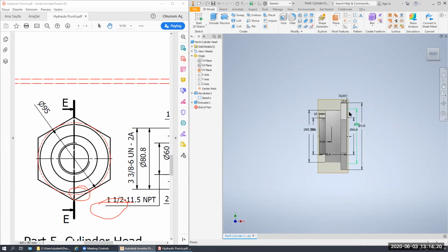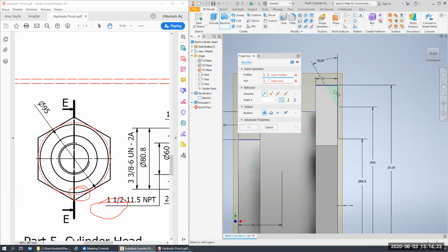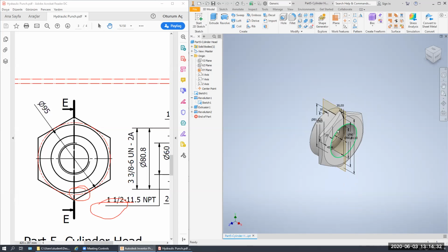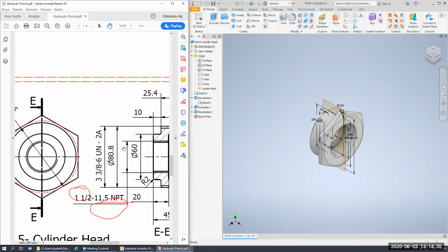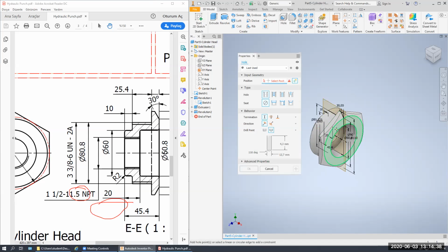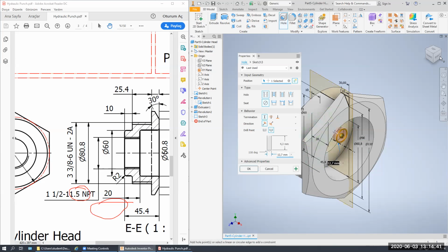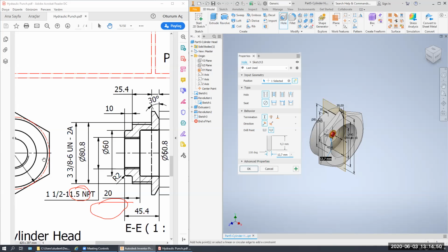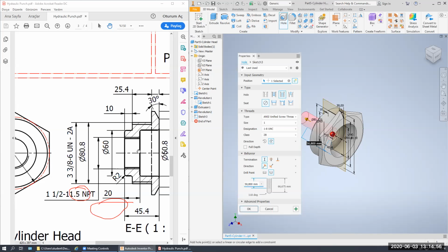This time, after I have just created this one, I have the revolve tool. Select this face, make this axis around with the cut properties in order to have a shape something like this. And also I will create a new hole with the threaded feature. Here I'm going to use the center point, which I have created with the dimensions that I have seen here. I will use a threaded hole, the normal stuff, because actually I do not use this one.